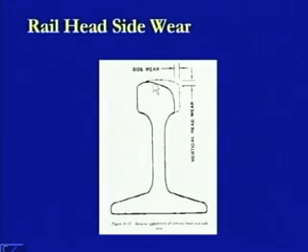So, what we can see in this diagram is one where the side wear has got affected. This is the normal section, as we can see in this diagram, and what is happening is that there are two types of things happening in this same section. One is a side wear by this much amount. This is the total amount by which the rail section has reduced, and at the same time this is going down, therefore, there is also this much amount by which this rail section has gone vertically downwards. So, these are the two types of wear which are happening at this location.